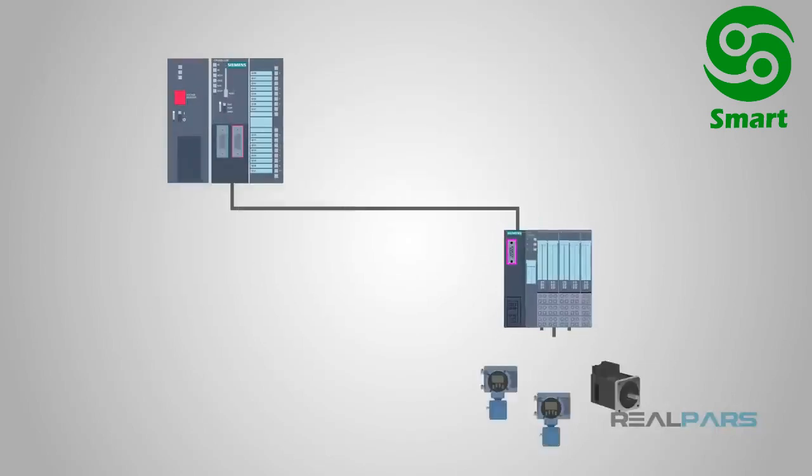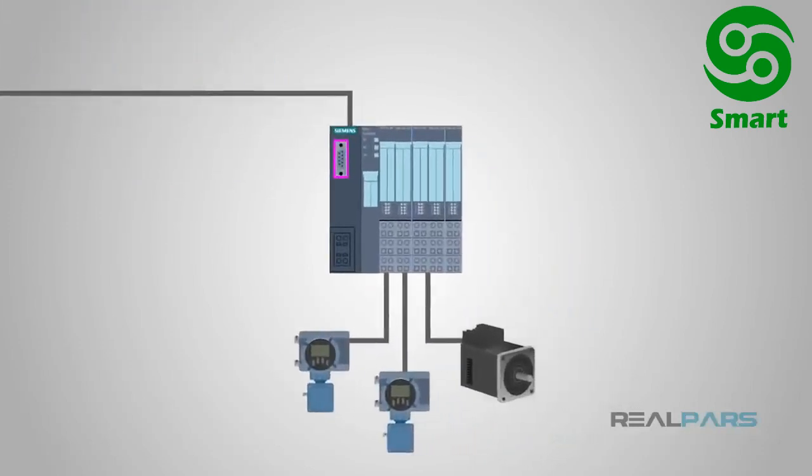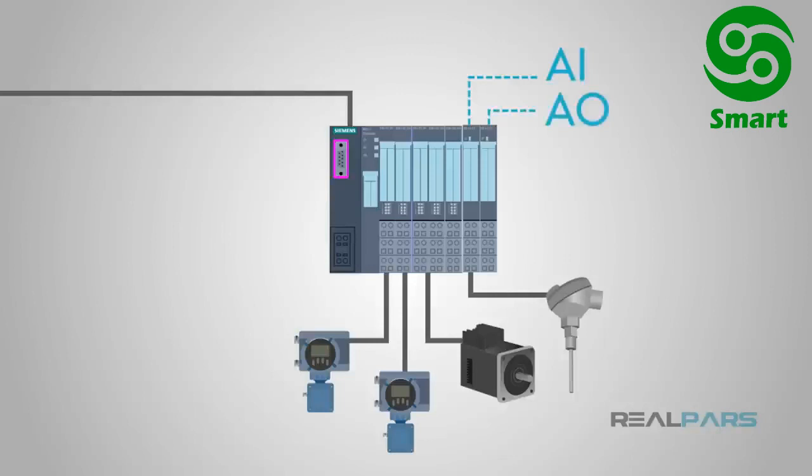In other equipment, the I/O modules can be miles away from the CPU and connected with data cables, so that the PLC is not limited to a single cabinet or even the same building. Since the PLC is a computer, there is no need to limit it to only digital inputs and outputs. Over the years, the manufacturers added analog and other numerical inputs and outputs.